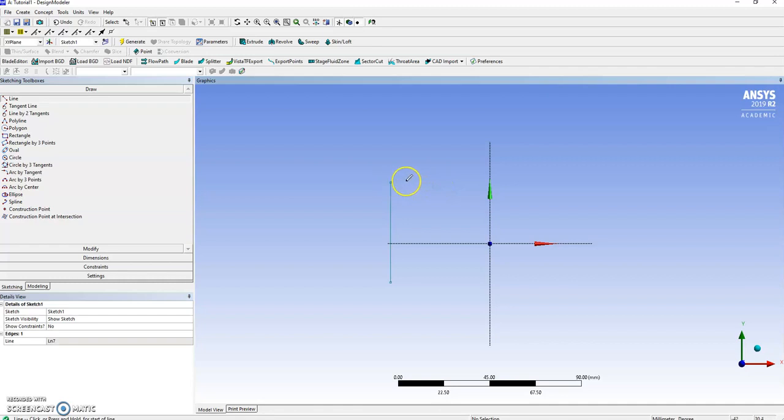Next, I go on the dot there to be on the P. P means continue from the point. I could be coincident with the line, even outside actually. But I want to be coincident with the point. Otherwise, you don't have a closed path. You're in trouble. So I'm going to create that. Horizontal, coincident point. I don't dimension anything at this stage. That's later. P. Horizontal. P.